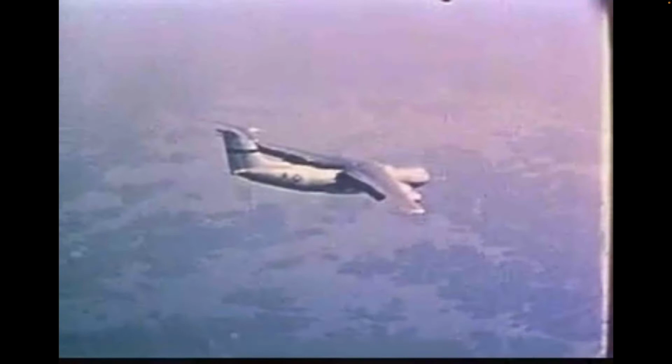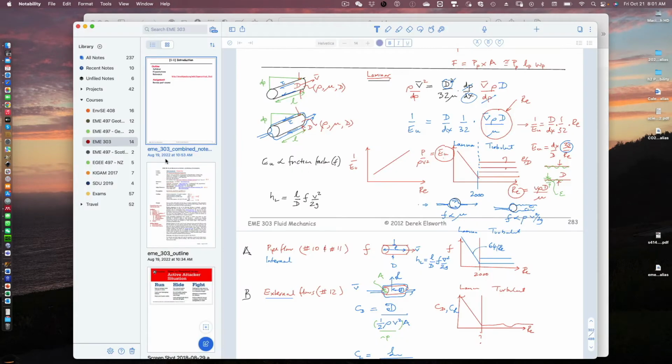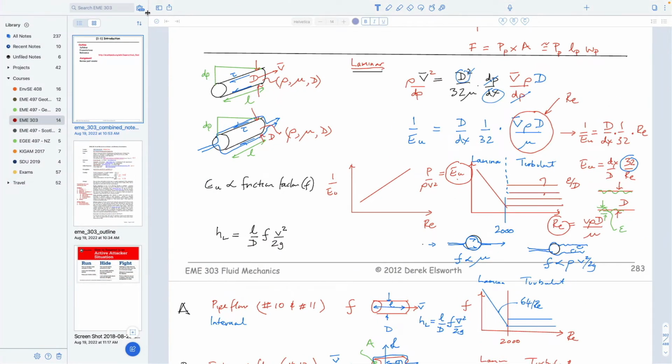You want to make sure that the Reynolds number of the scale model that you're flowing past in the wind tunnel is the same as you'd see in the prototype case. And then if that's the case, those are the kinds of scaled forces that you'd expect to have on that structure. Whether the structure is the same strength and rigidity as the real plane is an extra burden on you to explore, in addition to those fluid mechanics constraints. So that's kind of what we'll talk about in microcosm today. So that's just a preamble before we get on with our details.